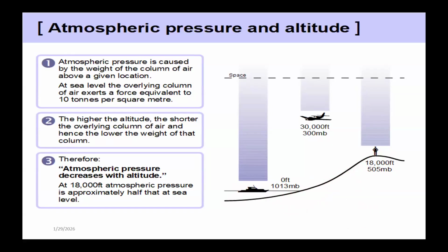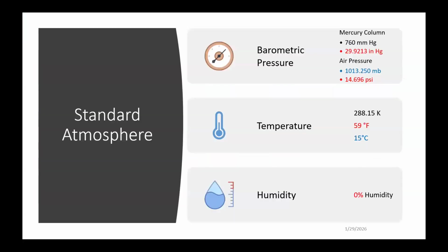If you were to try to calculate it linearly, and I looked at doing it for my home airfield, if it was a linear relationship, then the millibars at field elevation for Kelly Air Park, which is roughly 7,000 feet, if you did it on a linear scale, it would make it look like it was 7,700 feet. So it's a nonlinear relationship. Actually, we have our sea level standard number for Kelly is 781 millibars. So it's just off, like I said, it's not linear.